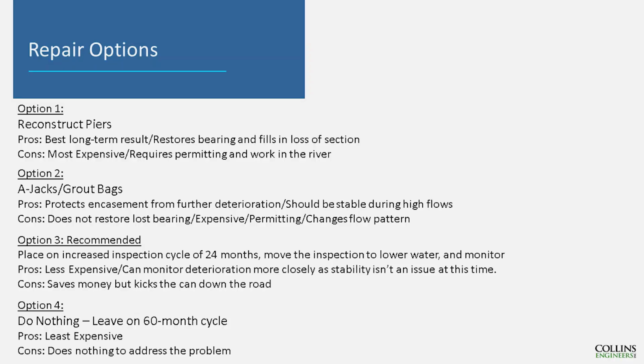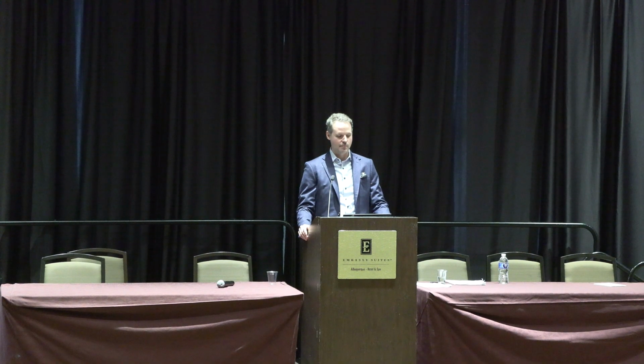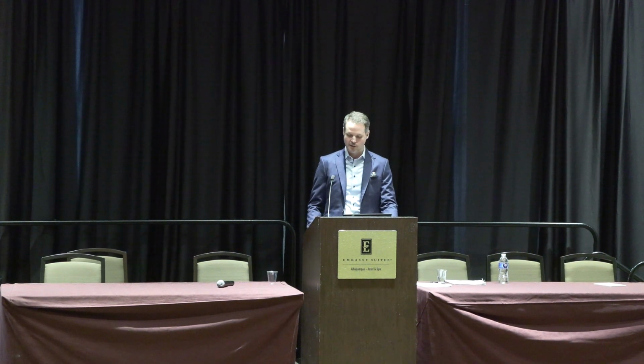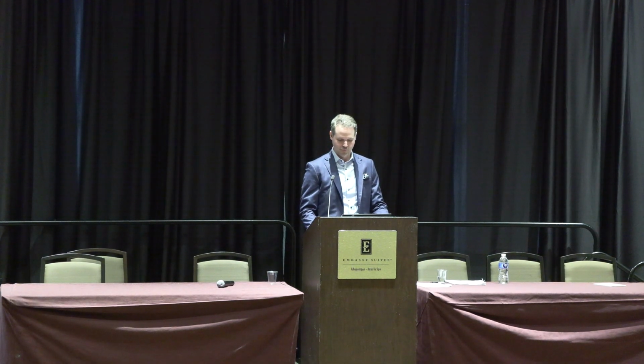Skip to option 4. That was just do nothing, leave it on the 60-month inspection cycle. Obviously that doesn't address the problem. What we settled on was simple, just increase the inspection frequency. Since we figured this probably wasn't a real critical issue to the bridge, it was probably better to just try to monitor it more frequently, since we weren't really concerned about stability. So this saves a lot of money not having to do a reconstruction, but kind of kicks the can down the road a little bit.